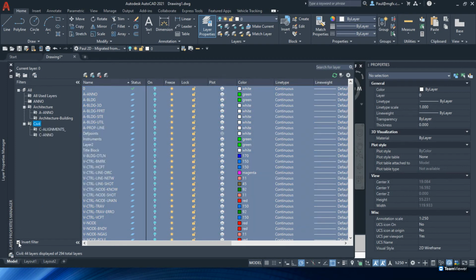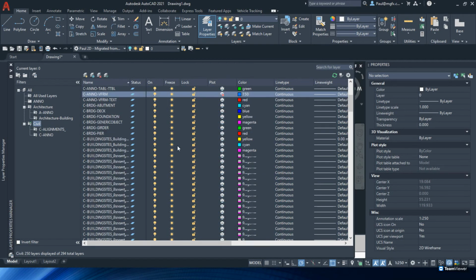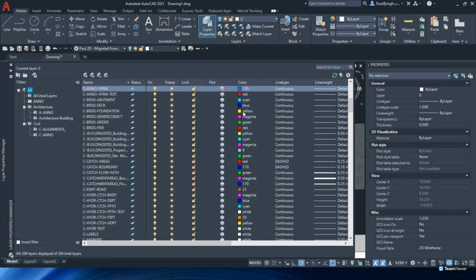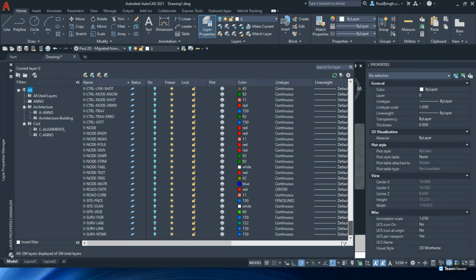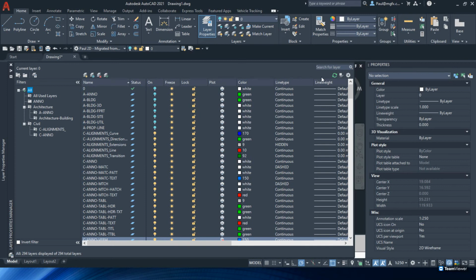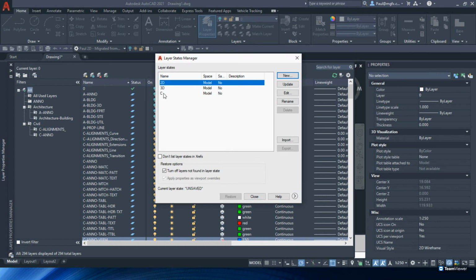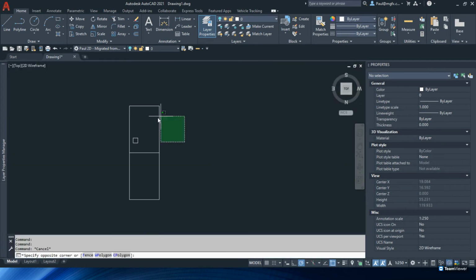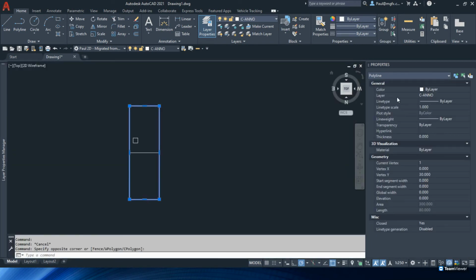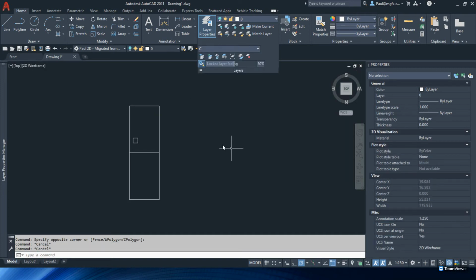Right, so you can select them. If you invert the filter, then you'll see what that looks like. And if you look at all of them, you'll see everything that isn't C is now switched off. So you can use the filter invert as well to isolate elements that don't comply to the filter and then set that layer state up. You can say, right, so this must be C. Let's update that. Yes. Those. Okay, so that was C. And again, we control the layer states from here.